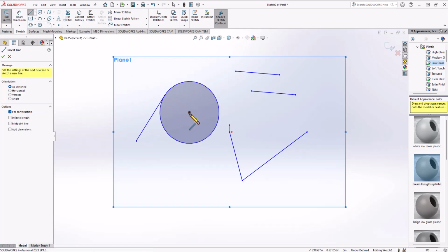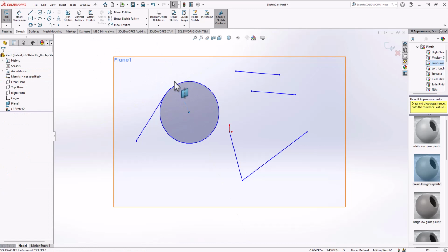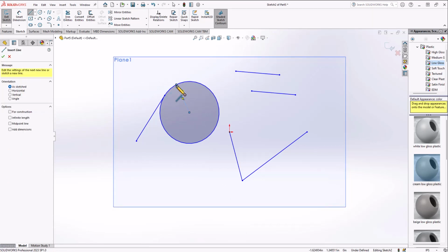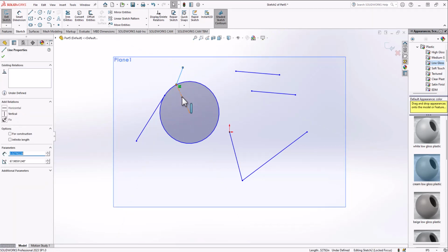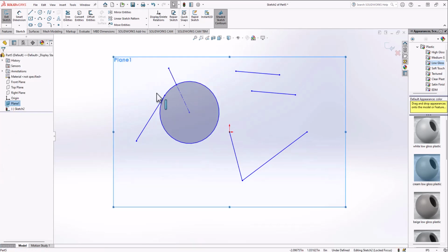But what you can do is draw a center line, so a construction geometry from the center of the arc to the arc. And then if I do that and draw a line, I can make this collinear with this arc. And that's how you make it perpendicular to the curve. So that's kind of how you do constraints and stuff. For everything, those are pretty generic.